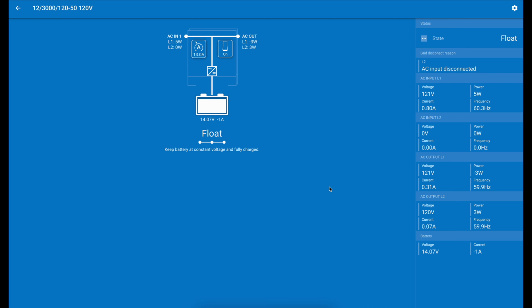If your inverter system does not display this data, then the only way to glean this would be to use a multimeter, because specifically here we're going to be looking at the voltage and the frequency of the power coming into the inverter system. Quality of power is usually the number one reason for inverter no connect. So this is certainly the first thing to check: what is the voltage and what is the frequency of the power coming in to the inverter.